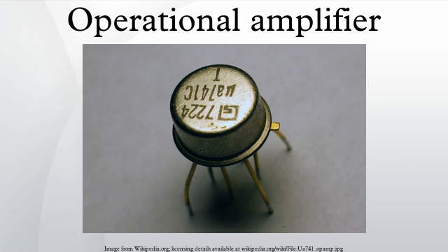Power supply rejection. The output of a perfect operational amplifier will be completely independent from ripples that arrive on its power supply inputs. Every real operational amplifier has a specified power supply rejection ratio that reflects how well the op-amp can reject changes in its supply voltage. Copious use of bypass capacitors can improve the PSRR of many devices, including the operational amplifier.